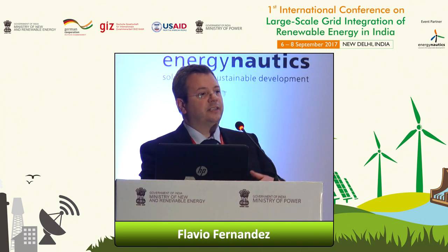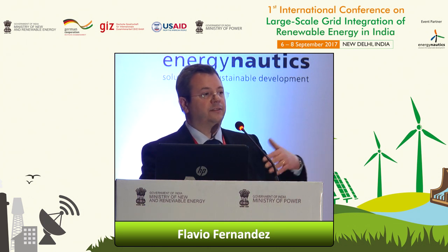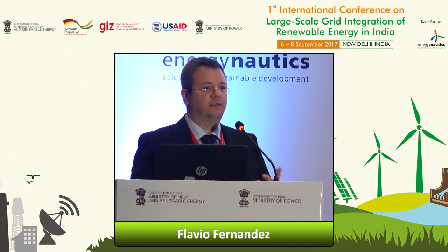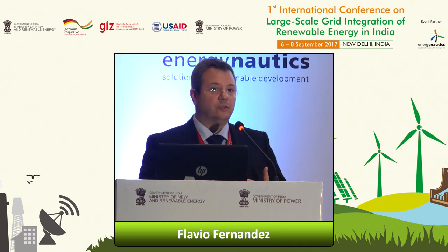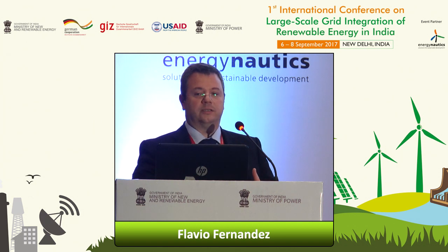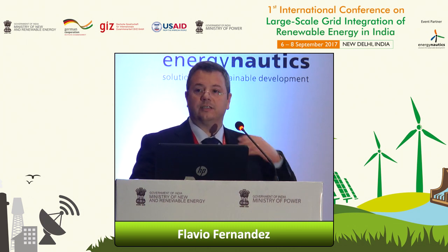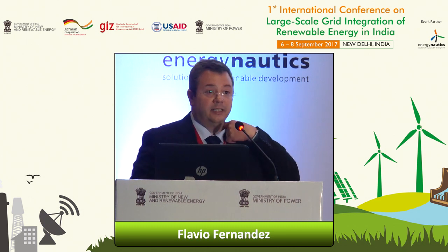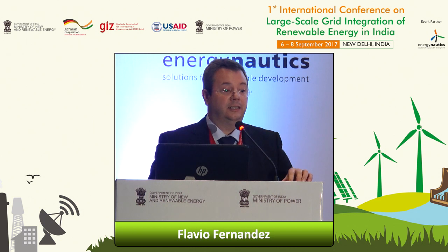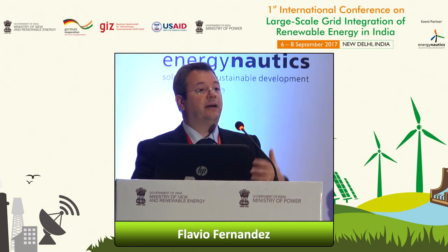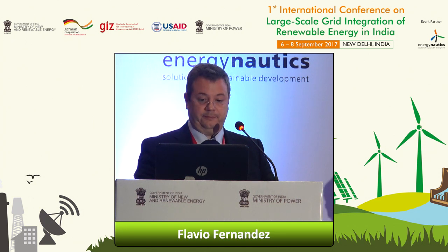So in terms of network planning, if you're looking 20 years or 15 years ahead, you do not even know which technology you're going to use, depending on the manufacturer, etc. So the generic models are actually a good approach in terms of doing the analysis. You can follow and say, well, depending on the grid code, which functions, which ancillary services, etc., you can expect from the plant, and parameterize the model based on that.